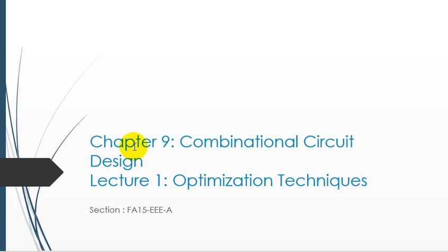And in this chapter we examine techniques to optimize combinational circuits for lower delay or energy. The vast majority of circuits use static CMOS because it is robust, fast, energy efficient and easy to design. However, some certain circuits have particular power or density restrictions that force another solution. Such alternative CMOS logic configurations are called circuit families. So the main target in this chapter is the circuit family.